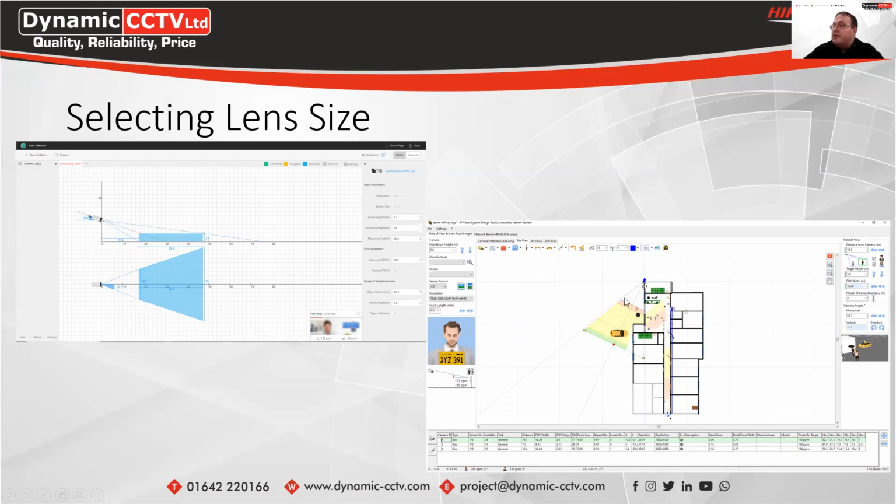And you can set in your different heights and the lens sizes, and that will affect the overall coverage of the cameras, and that will give you a visual representation which you can then take to your clients after you've done the design and submit that as what the system will be able to achieve on paper within a report. So it's a great tool that we use quite a lot as well, especially when we're helping out customers to be able to work out which lens size fits right for their site that they're looking at.